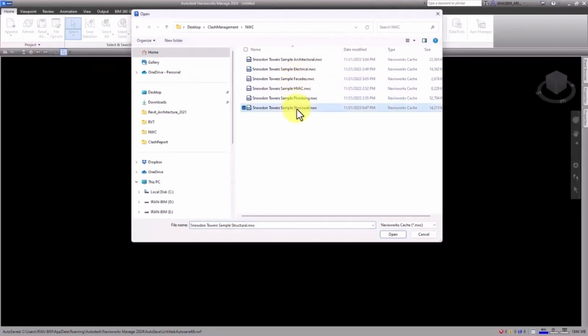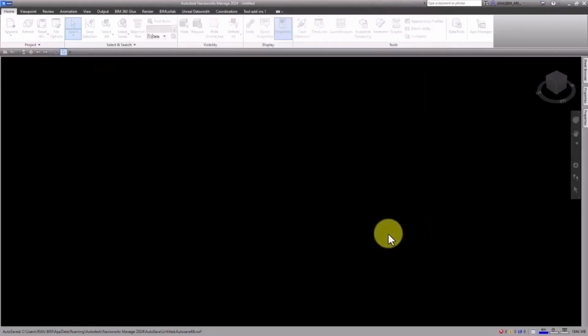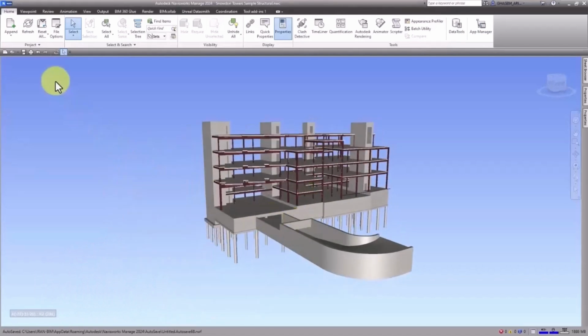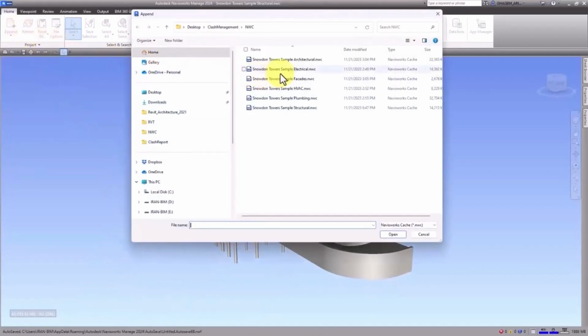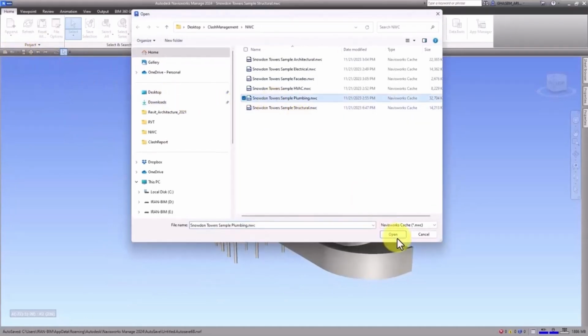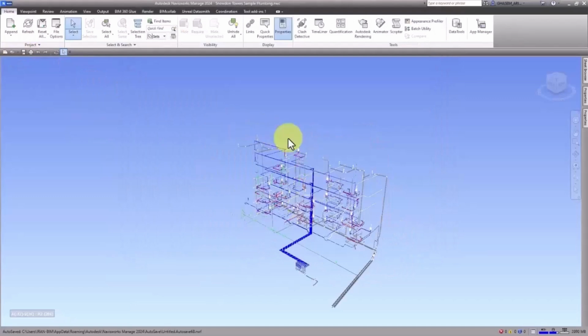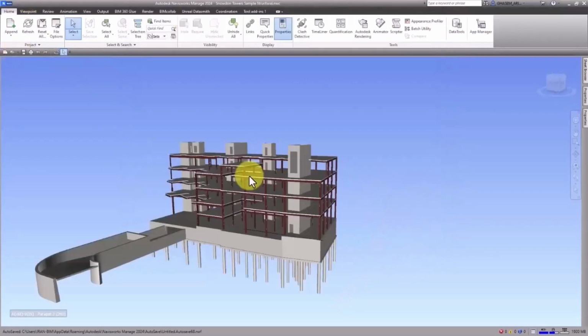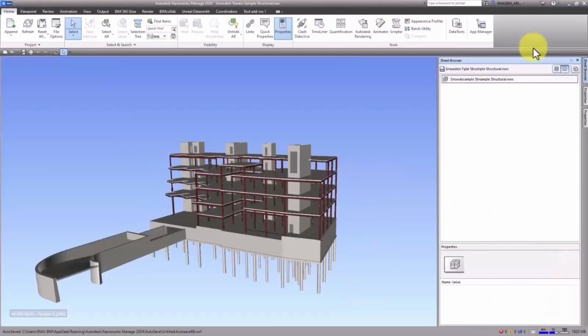Here, open the desired file, and usually simple slowdown. Open it, like this. Other disciplines should be open here. It's not possible to open another one anymore. There is a restriction about it. In Navisworks, you can only open one file. When I want to open another file, the previous one will be gone. So, only one file. Unless you use sheet here in this section.